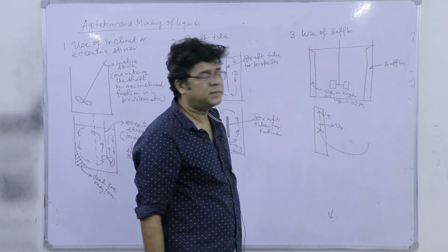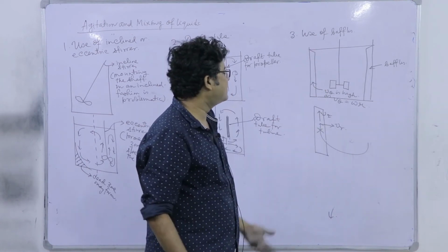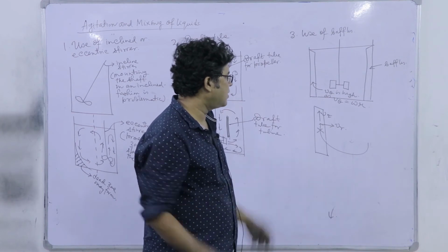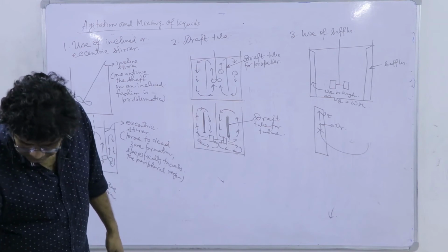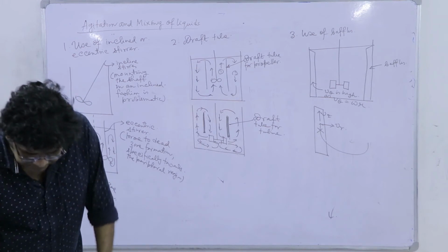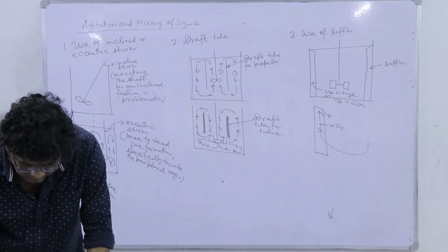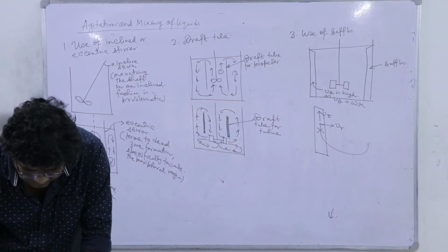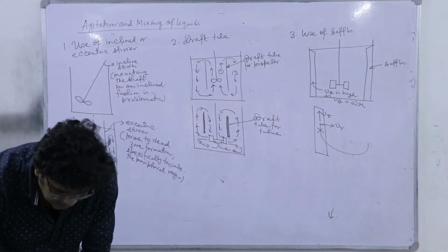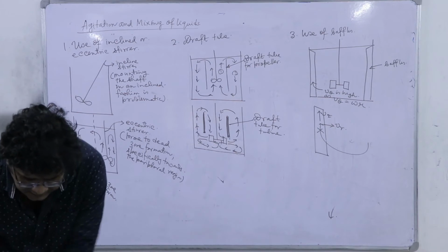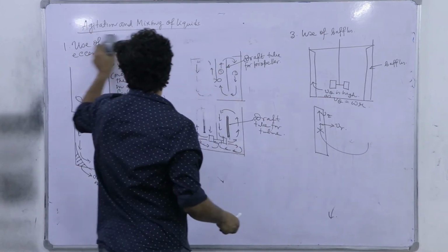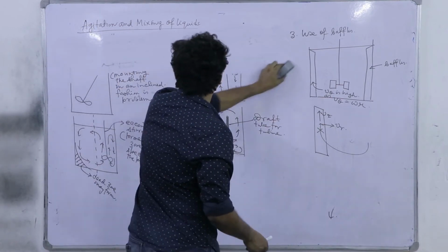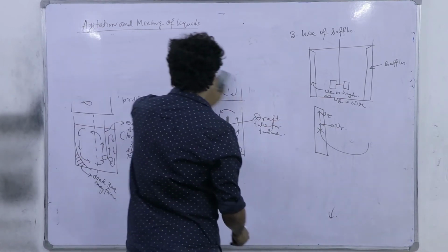We can use multiple numbers of baffles, 6, 8, 4, etc. For smaller tanks, we go for 4 baffles. More importantly, we have a standard design for these turbine fitted tanks. I am not asking you to remember what my optimal shape ratios or shape factors should be.